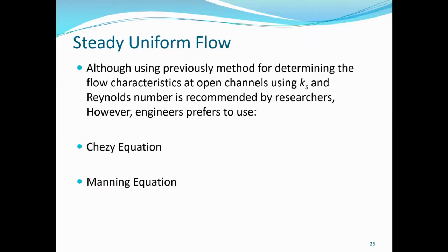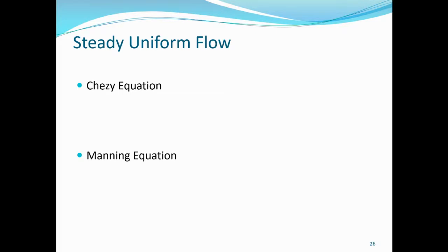However, engineers prefer to use the Chezy equation and Manning equation, and they are limited to uniform flow and normal depth. Normal depth is the depth of flow for uniform flow. We call it normal depth, yn.